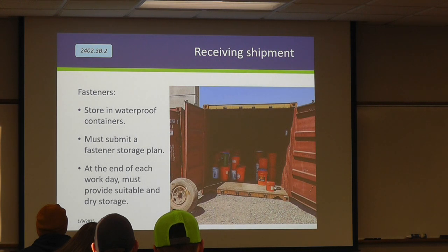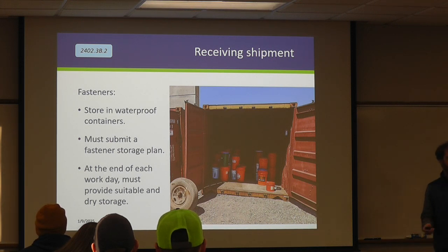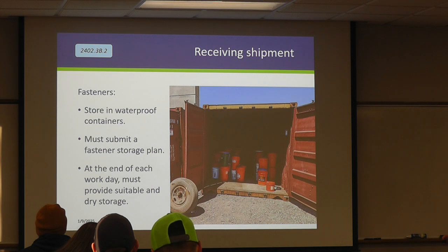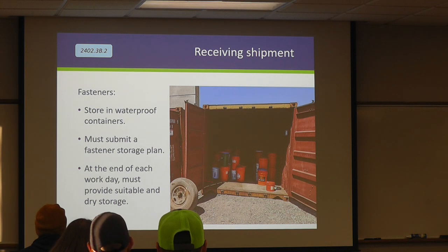Your fasteners themselves, we've had such a problem with contractors not treating these fasteners appropriately that now we require a fastener storage plan. This is a submittal that they have to go through to show us, or to commit to us that they're gonna actually take care of these things. It's simply, most generally I see Connex boxes with all the bulk kegs put in there at the end of each shift. So it's not like this is a super onerous thing.